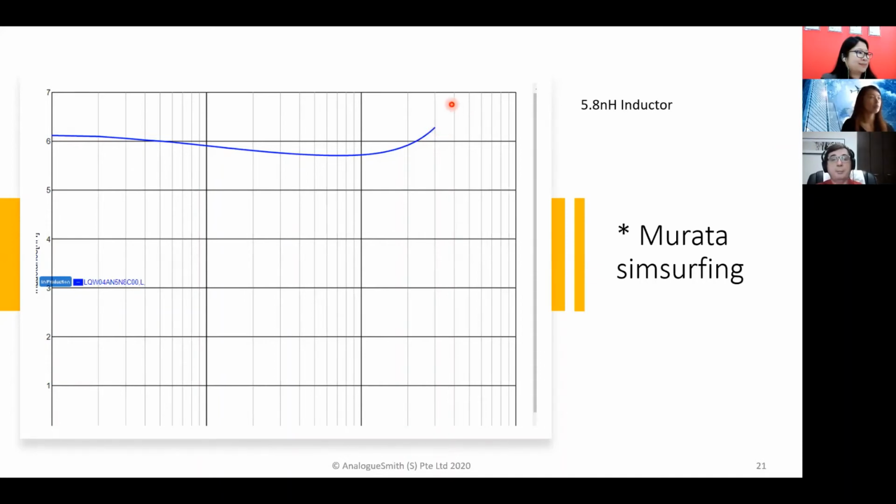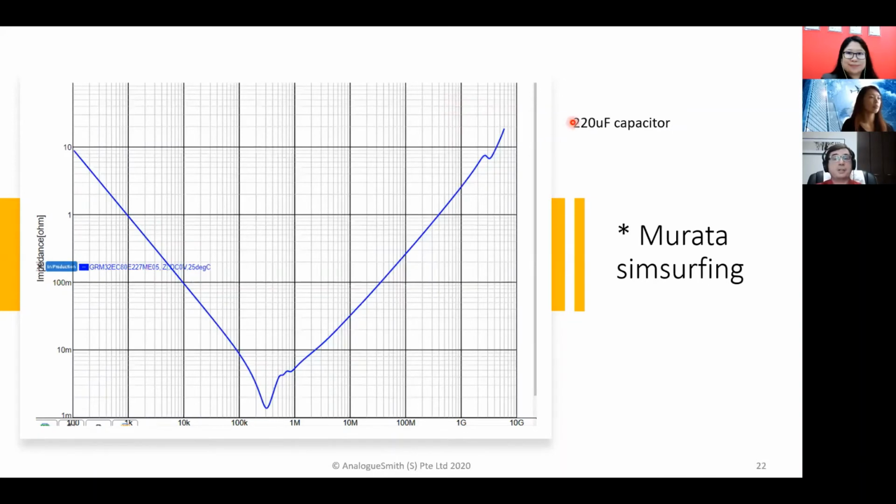So what we can do is we can also look at the value of a capacitor. Now, here's a large capacitor. So you say, right, I want a very low impedance, so I want a really huge capacitor, okay? And you take that large capacitor, in this case 220 microfarads, and you plug it into your circuit. You should look first. Here's the impedance of the capacitor over frequency.